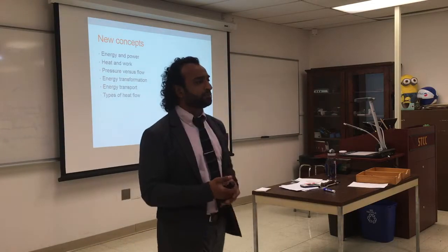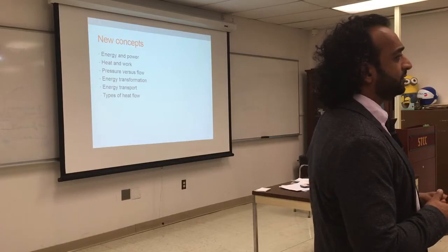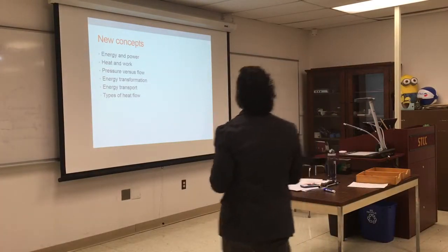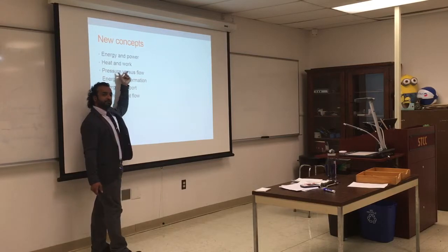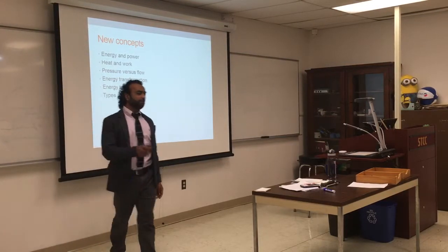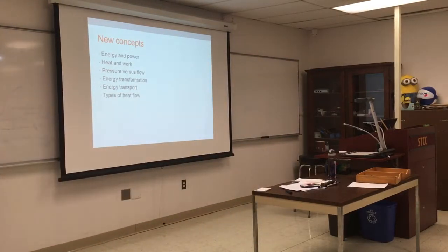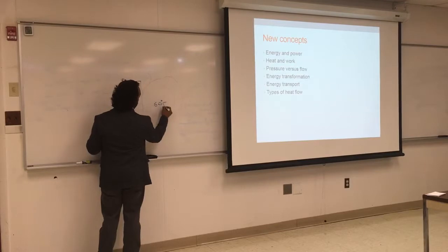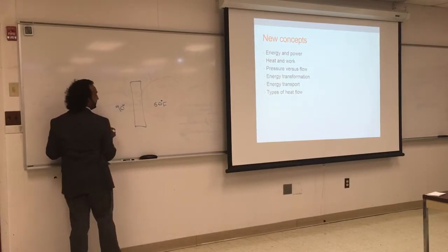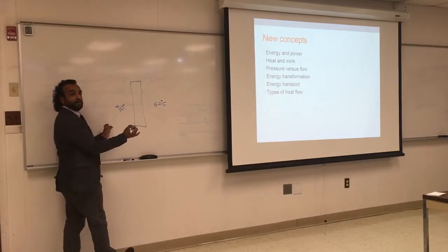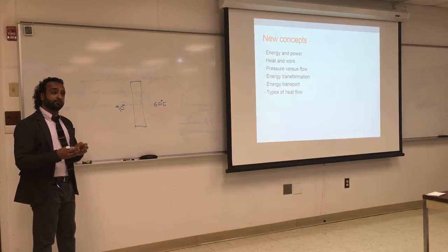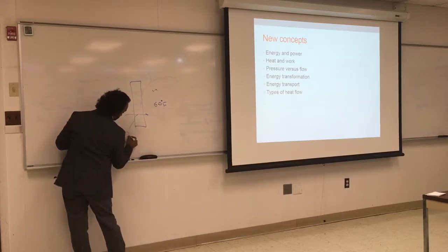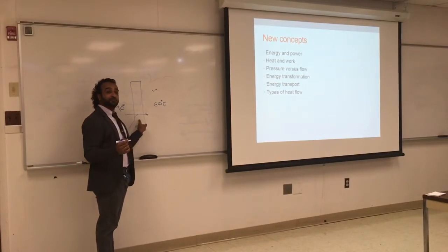From the last class, we were saying, if pressure is voltage, what is flow? Current. We're going to use the same analogy with heat. If we have heat as our energy, and the amount of heat is pressure, the flow of heat can be like current. So thinking about that, if this is a wall, the inside is 60 degrees Fahrenheit, and the outside is 90. If we think of heat as energy and as pressure, which direction do you think the heat will move from? Outside to inside? Yeah, it's going to move this way. This is going to be my flow. And would this be my resistance?